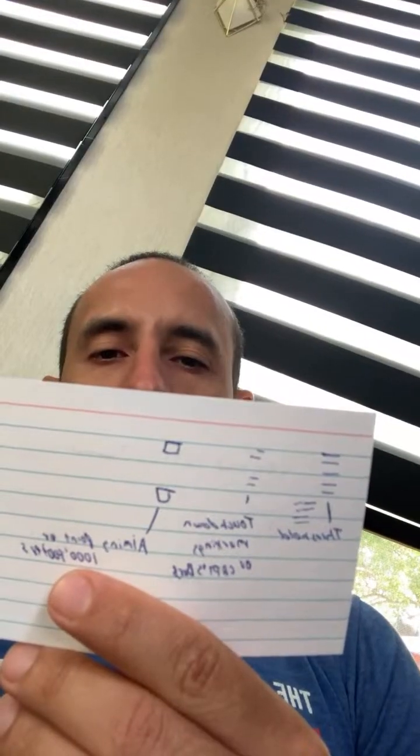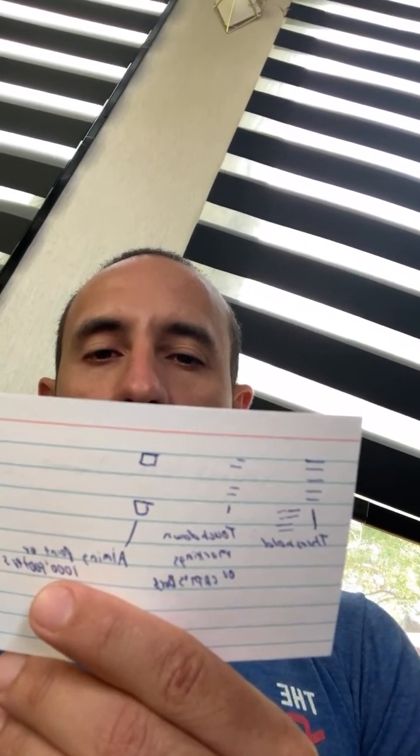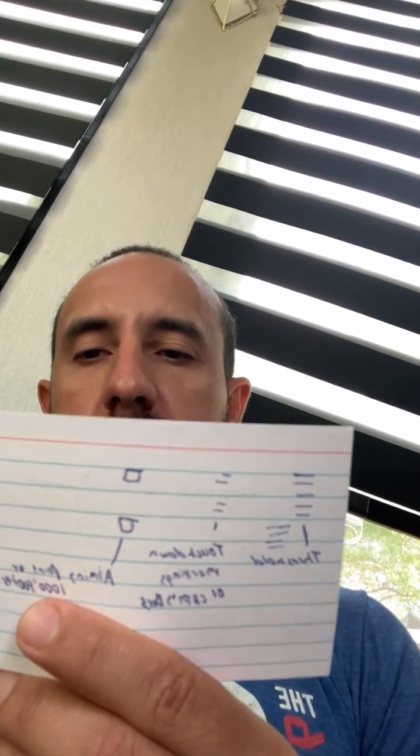What are the various runway markings? So you have the threshold lines, the bunch of dashed lines at the beginning. You have the hold short line. You have the touchdown markers or captain's bars, typically around 500 feet. And then you have the aiming point or 1,000 footers.